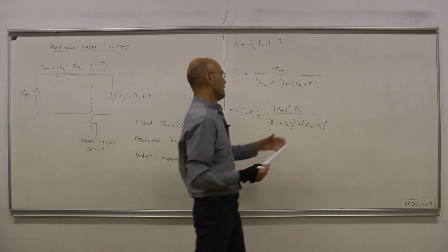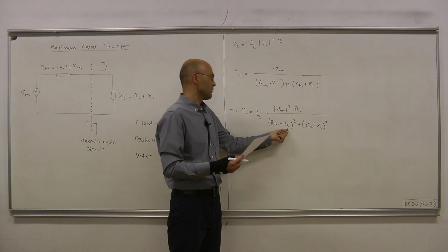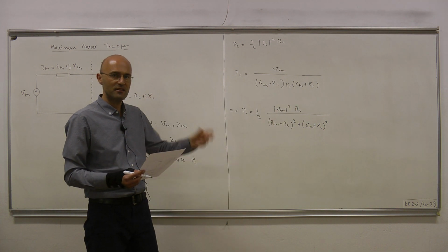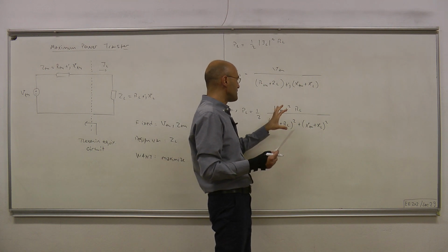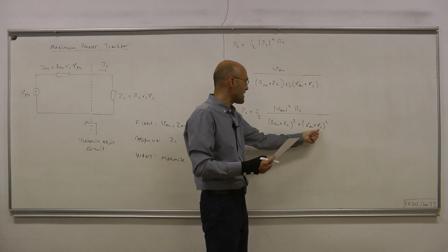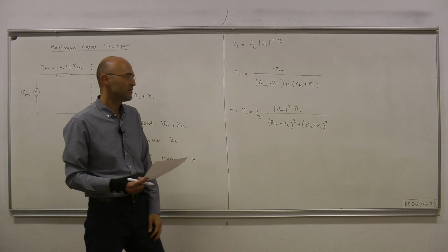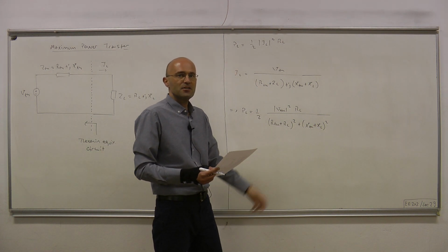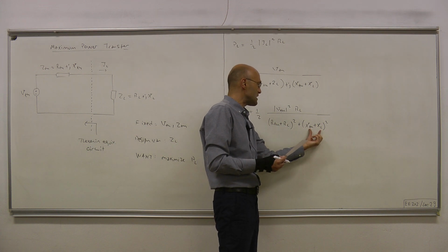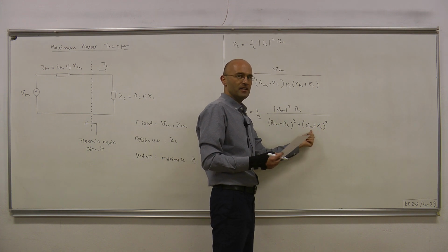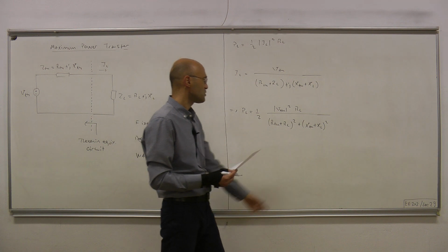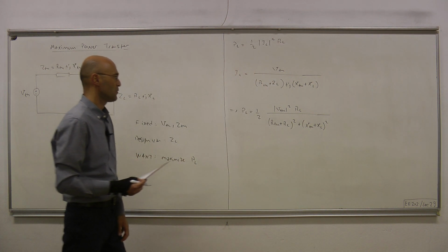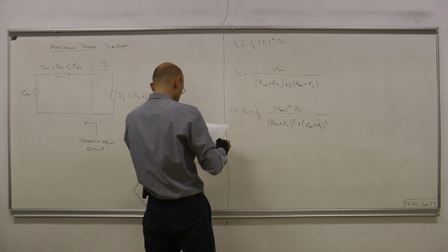Of course, RL also appears in the numerator. So how to choose RL at this point is not clear, but since XL does not appear in the numerator, we can choose it freely, with any sign we want. It can be chosen to equal in magnitude X Thevenin and opposite in sign, so that this term can be made 0. That seems like a reasonable first step.